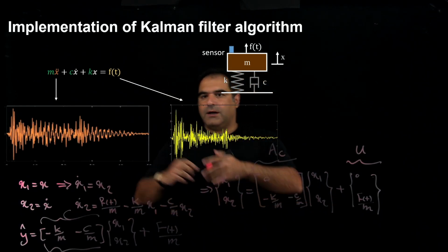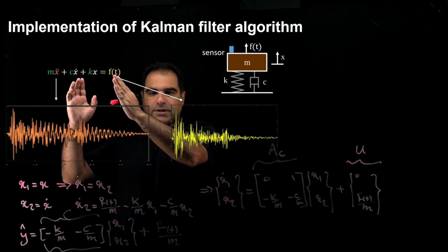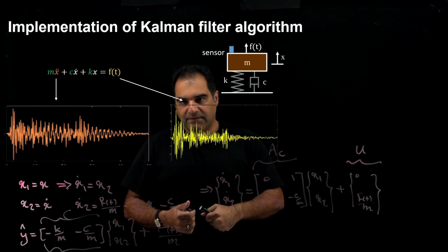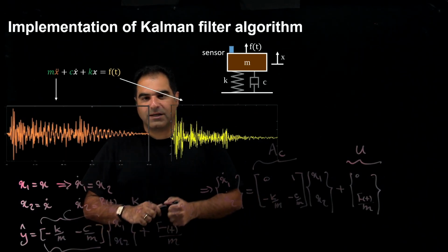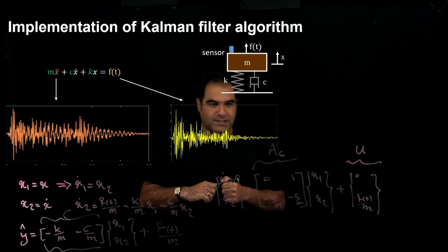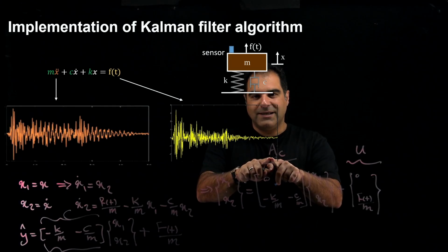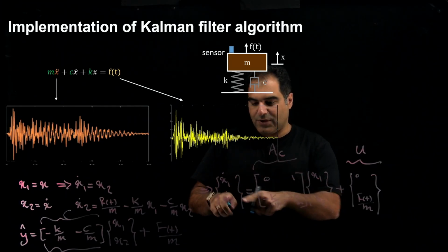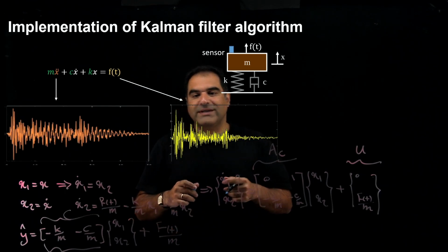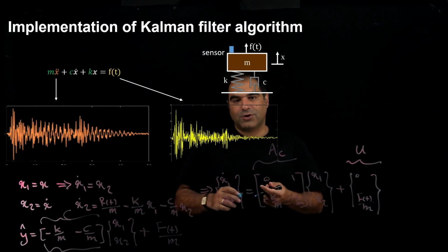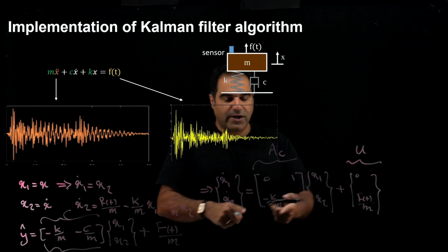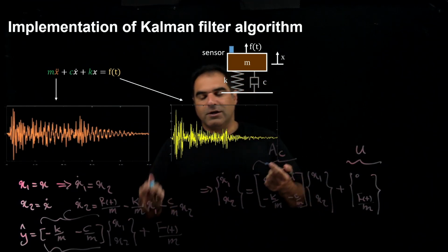You see, I was able to write my second order ODE into a state space form and use it in the Kalman filter. But before jumping into the Kalman filter algorithm to follow the steps, I need to mention one point. This A matrix I calculated, x dot, is a continuous form of the state space model. We need to convert these to discrete form because the Kalman filter algorithm I wrote was in the discrete domain. Then the first option people usually use to discretize a continuous state space model is either Euler.